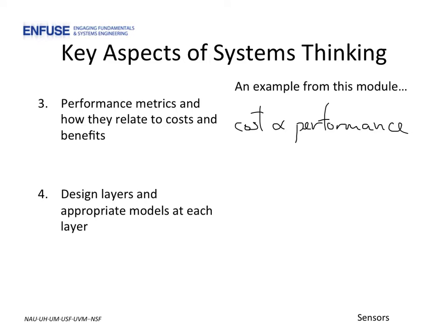We discussed the idea of design layers indirectly when we considered strain gauges. While the highest layer objective of the system is to understand the mechanical forces on the structure of interest, this we do not measure directly. Instead, we designed a system that can be considered at a much lower layer and that uses a change in resistance in a gauge.